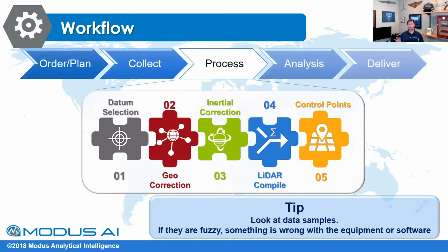And the last part of your process should be control points. You should have software in there so when you set your control points, you can find them in tabular data of where you've actually set your points. And if you've used the right targets, you should be able to see them in your LiDAR data and have tools to find that exact center so that you're spot on in your data reports. So I'll leave that saying, really look at how they flow through a problem and see if this actually matches what your workflow and your culture does and integrates with your flow.